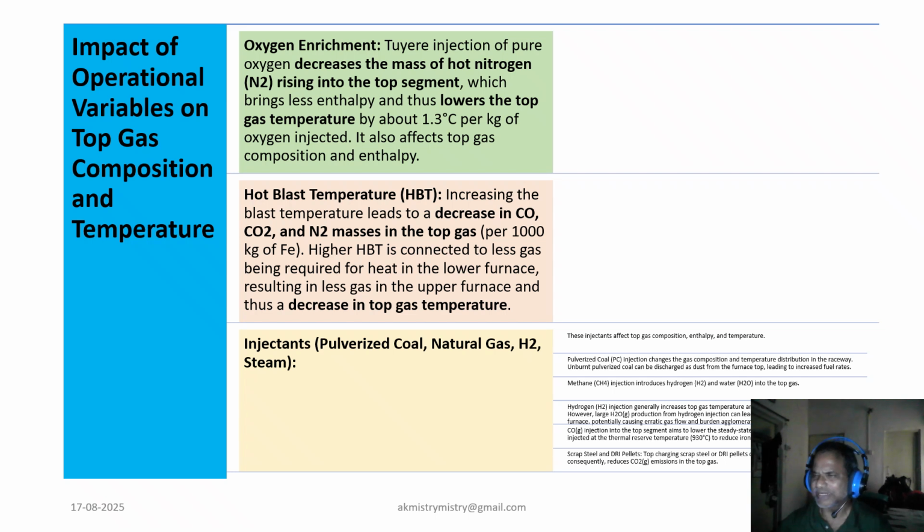Now, let's connect this to the core chemistry inside the furnace. Hot CO gas continuously ascends and reacts with descending iron ores, producing iron and CO2. This process is known as indirect reduction. The CO2 percentage in the top gas specifically indicates if this indirect reduction is occurring. As iron oxide is reduced by CO, CO2 is formed, directly reflecting the progress of this reaction.